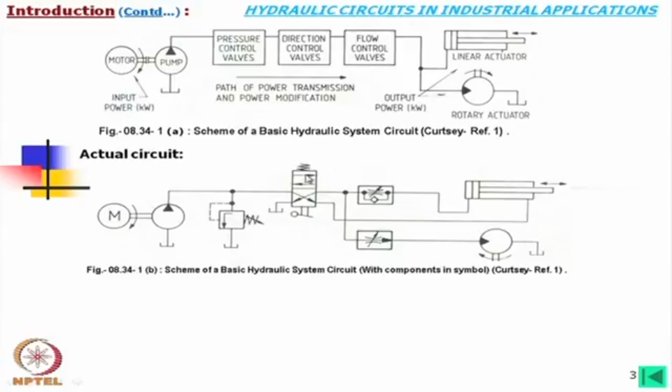Whereas if we connect this one, oil is going through this, and this arrow means we can vary this, that means we can control the flow. So, there will be a controlled flow for actuation. This means that depending on load we may control the speed also. In that case this is a fixed displacement pump, but still this velocity can be controlled.